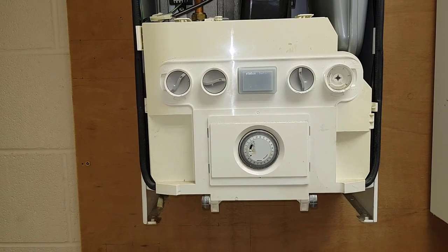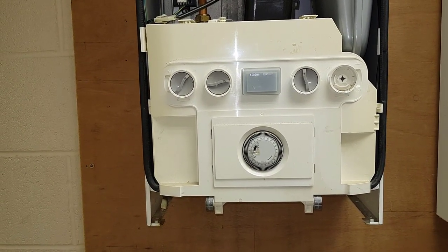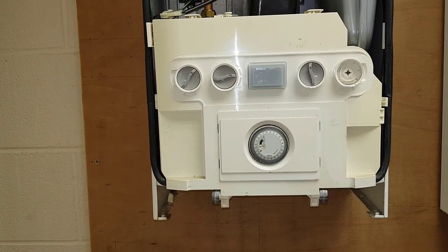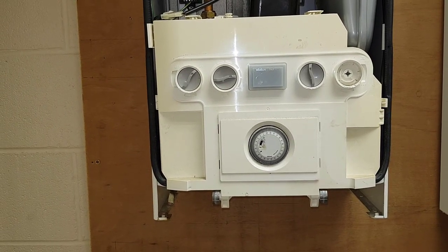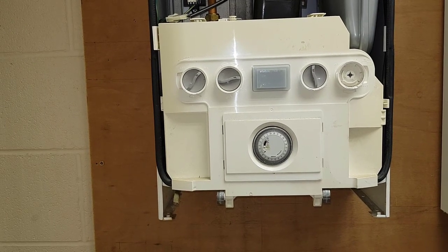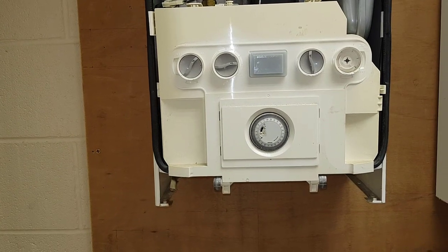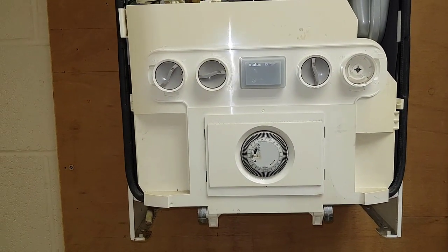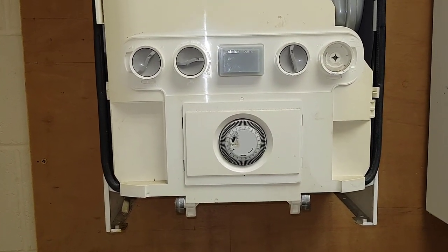Right, so a customer calls you and says that they've got no central heating. It could be anything. But because you've got your framework to help you diagnose, you look at your quadrant. One of them is a possible timer or room thermostat. Yeah, that's right. So what would you be looking at on this boiler, this Ideal, on the timer and room stat? What would you be expecting?